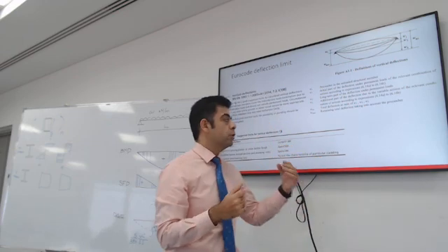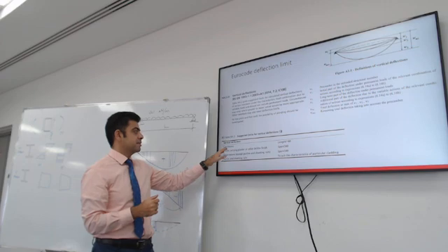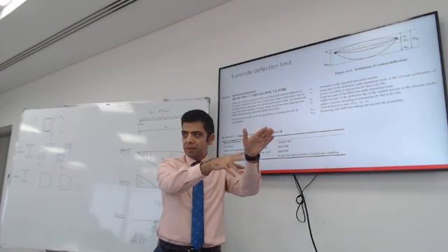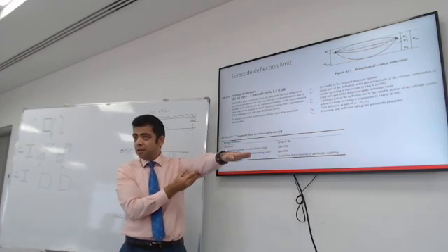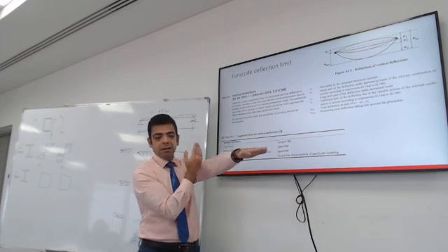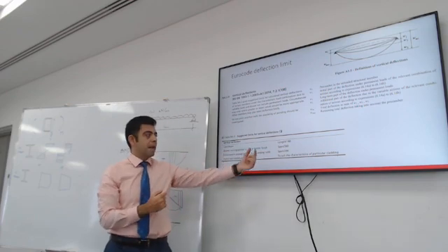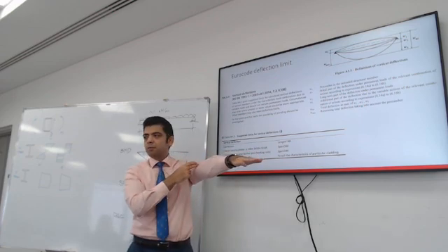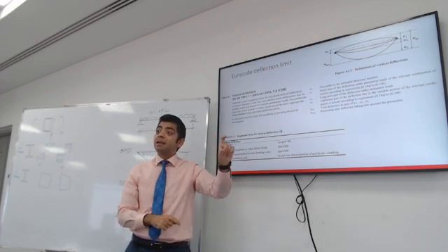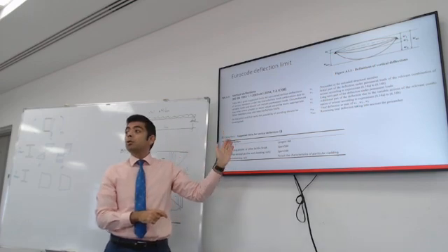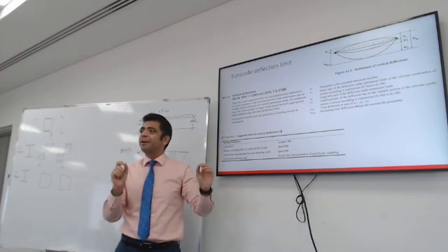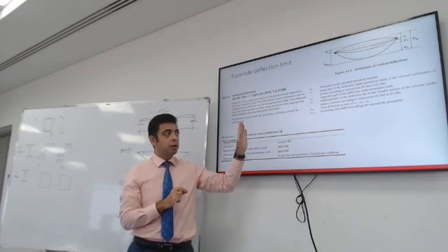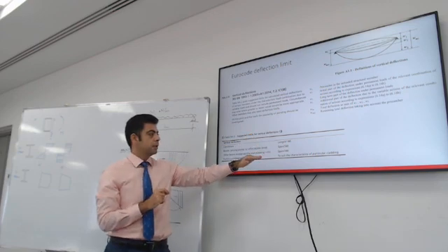So this is how you interpret these limitations. For cantilevers, a cantilever is like a beam with an overhang, with a free side. If you have a balcony, do not allow the tip, the free end of the balcony, to deflect more than the span divided by 180. So if that cantilever was 3 meters, you divide it by 180, that's the maximum allowable deflection due to live load only. Eurocode will check the deflection based on live load only for the UK suggestion.